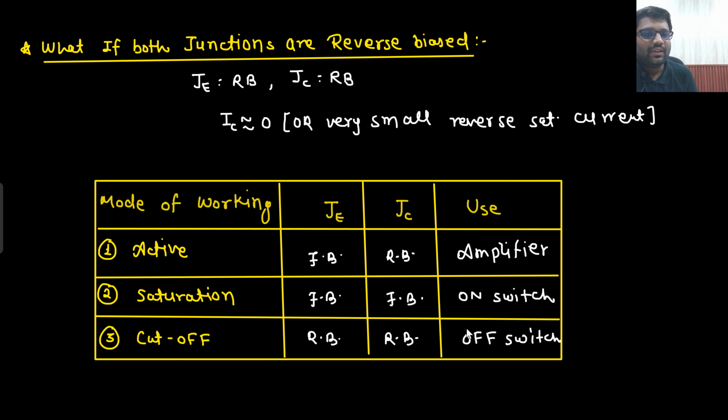But actually in analog we focus more on MOSFET. When we study amplifiers, we focus more on MOSFET because nowadays BJT is not used for amplification purpose. For amplification purpose, you use MOSFET. BJT is used in high frequency circuits. When you study high frequency analysis in analog circuits, although it is not there in your GATE syllabus,